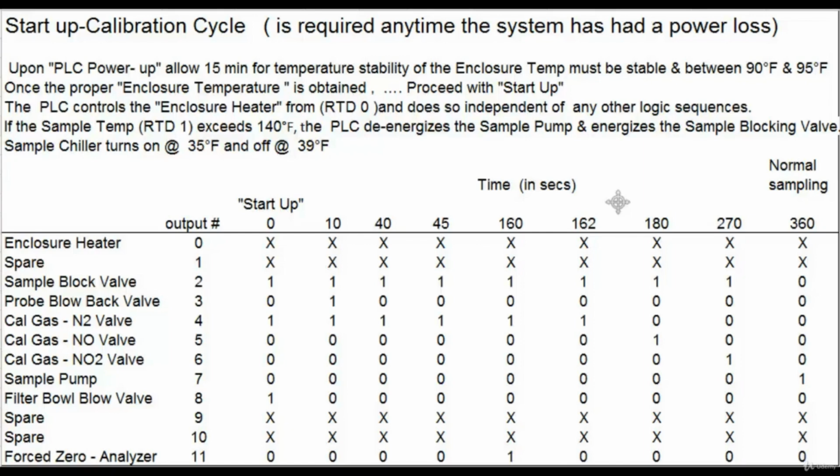Another thing we need to consider when we're putting process logic into a program is what are the contingencies? What can go wrong? If we're in the middle of a startup and all of a sudden an alarm condition arises, do we interrupt the startup? Do we sound an alarm and keep going? What needs to happen? What can happen all the way through our process?